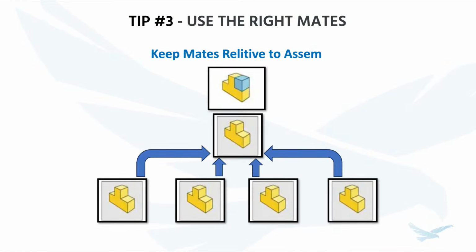Yeah, so our basic recommendation is to keep it simple. That's the same thing that engineers have been saying for a very long time. Use your basic mates, but use them in a way that's constructive to the design and doesn't get fancy unless you really need it. There are the mechanical mates. Those are getting into a deeper level of functionality, but a planar mate, coincident, concentric, all of these things are the bread and butter of how you should be mating.